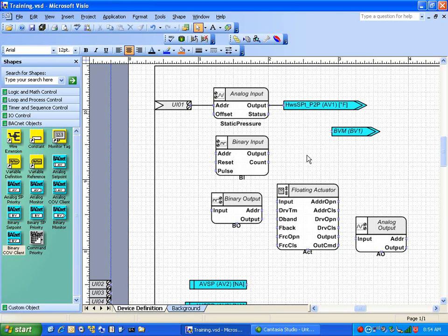Before I knew about the admin tool, every BACnet object I was creating, I was manually going into it, and really just every BACnet object got individual attention up in the UNC, and that's how much work it took. But now by making your Workplace Tech applications a little better, I can really avoid a lot of that extra work.